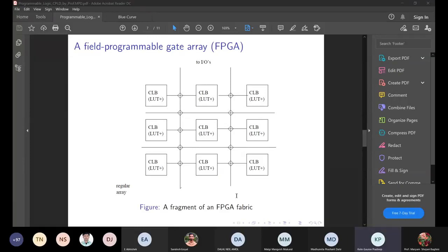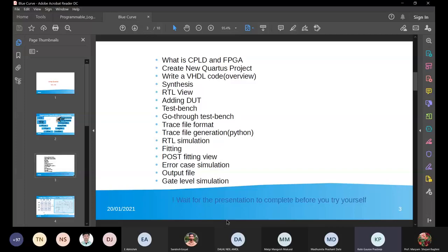So there are some main disadvantages of FPGA, that FPGA is a volatile kind of design. I mean, once you power on your FPGA, you have to program it again. Once you power off, it will lose all its program, or all the design that has been entered into an FPGA. So you have to keep on reprogramming it when you power on your FPGA.